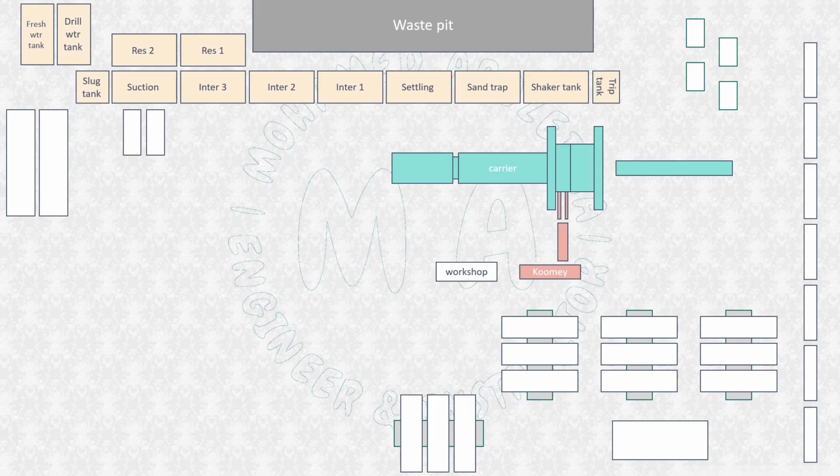It should be aligned with the flow line coming from the subbase. Enough distance has to be kept from the waste bed to avoid the collapse of the bed walls due to high loads of the mast system. These are mud pumps. A concrete slab is required to support the mud pumps load and absorb the heavy vibrations of mud pumps, which helps in keeping mud pumps aligned to the mud system at all times.